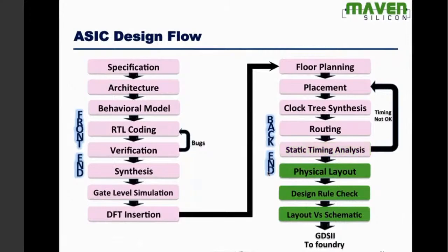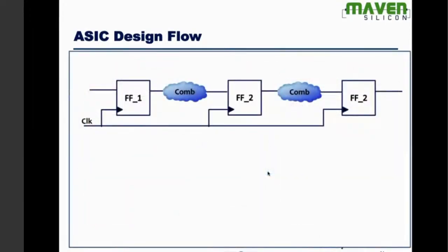Okay, now we have made the connections. It's time for us to verify the timing. So this process is called static timing analysis. During synthesis, we also verified timing, but it was not the actual frequency. But now we have done the routing. We have come to know about the actual wire length. And this is the right time for us to verify the actual timing, whether the chip is going to work at the expected frequency. That's what we are trying to verify.